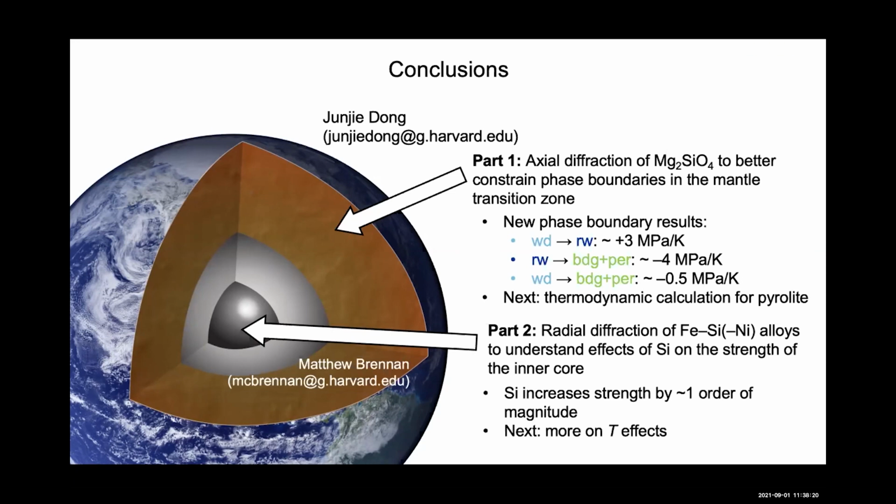No, that is not extrapolation. I can tell you one thing. For example, diffusion creep is grain size sensitive. Dislocation creep is not sensitive, so you cannot extrapolate. At room temperature, I'm pretty sure you're looking at the Peierls stress, and Peierls stress has nothing to do with diffusion, nothing to do with high temperature plasticity. So even then you cannot extrapolate. You have to understand that when you do those experiments to ask some question about the inner core.